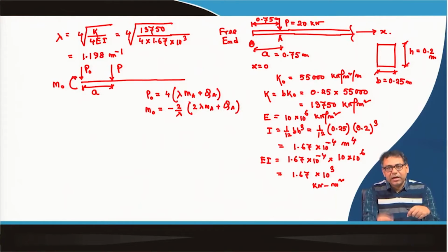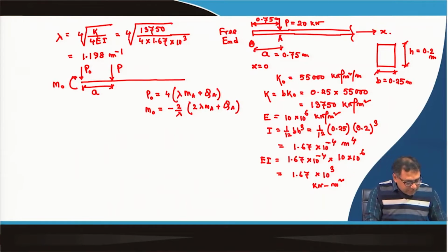QA is the shear force induced due to the load P if this beam is considered as an infinite beam. But actually it is not an infinite beam, it is a semi-infinite beam. So, at the free end we have to apply conditioning forces such that MA and QA will vanish, because that is the free end condition: moment should be 0 and shear force should be 0.